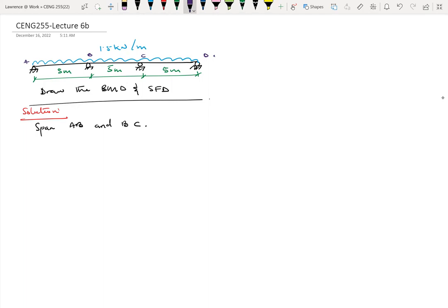So if this is A and this is B and this is C, my bending moment diagram looks like this. It should be the same anyway. And then the highest point here is WL squared over 8. So I don't need to go through first principles, find reactions, and all of that if I can find my moment diagram. At this point we should look for these shortcuts.